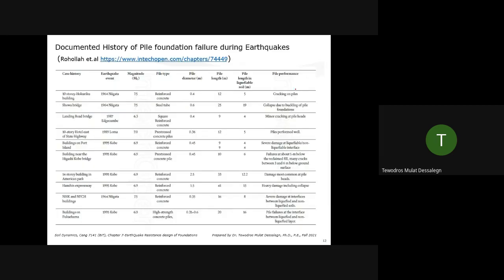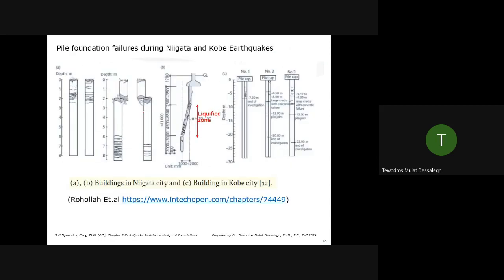So, documented history of pile foundation failure during earthquakes. There are so many pile failures recorded in the past. You can go through this link or see this table. So many things were reported in the past. And in some cases, you can see figure A. This is what they observed. After the damage, they went deeper, up to 80 meters, into the piles, but usually it's shallow failures and even around the rock where they are, because it's liquefied, and even at the top area breaking.